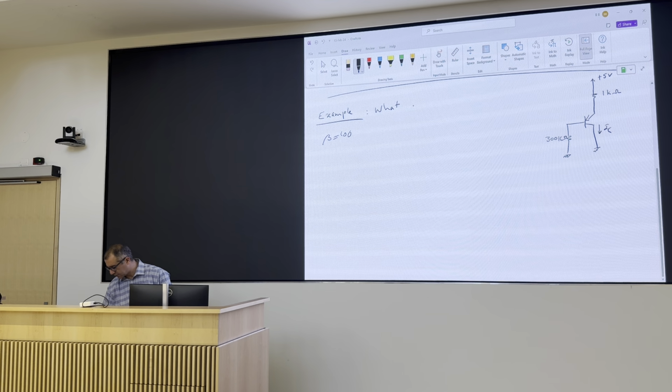Because remember, this is my controlled source. This is where hopefully all the interesting stuff is going to happen. Right? So IC is usually the desired output, or the one that gives me more information about the stuff that is going to happen. So if this is the case, and I start to play with these two voltage sources, I can see a few things. So first of all, let's say you put a VC of 1 volt, 2 volts, something, to make sure the device is not saturated, and then you change VBE. And what you expect to see